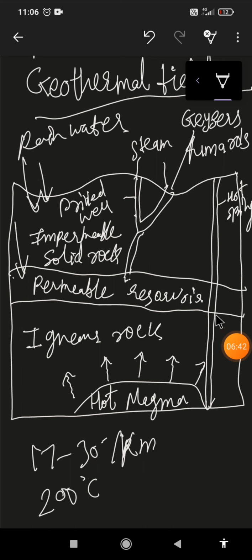So geothermal gradient. What is the geothermal gradient? It is defined as the rate of increase of temperature with depth. In a developing country, to use geothermal energy, a few factors need to be analyzed. First, the variation of temperature with depth in different parts of the world. Then identification of locations at convenient depths from which it is possible to find water having a temperature higher than 50 degrees Celsius. And identification of rock that is sufficiently hot and impermeable, which allows extraction of heat economically and feasibly.